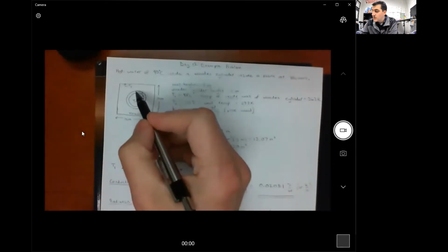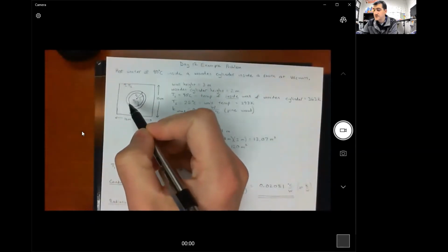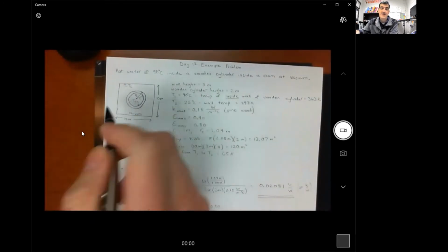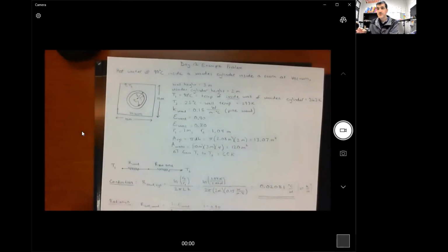The space resistance, well, now that's going to include the area and the view factor, but that's not going to be a problem either because I know the areas and the view factor. Well, look, this is entirely inside the room. So the view factor here is going to be 1, just like we had in the homework that was due today. The view factor is going to be 1. So that's no problem either. Calculating the surface resistances and the space resistances, no problem.